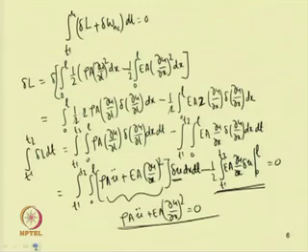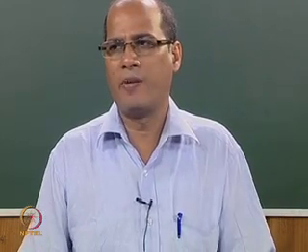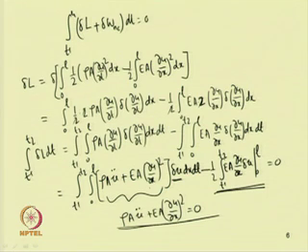Similarly, one can derive the equation of motion for other similar systems, and the advantage of using this Hamilton principle over the Lagrange principle or Newton or D'Alembert principle is that, in addition to getting the equation of motion, one can get the boundary conditions also. So this gives the boundary condition, E A ∂u/∂x into δu from 0 to L. That gives the boundary condition.